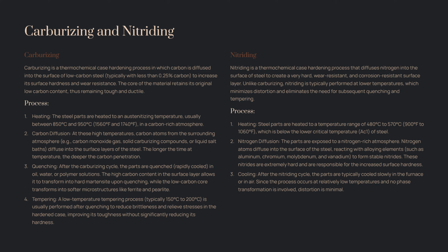Mechanism. Simultaneous diffusion of carbon and nitrogen from a controlled atmosphere. Result. Hard case with improved hardenability, reduced distortion, commonly followed by quenching and low temperature tempering.